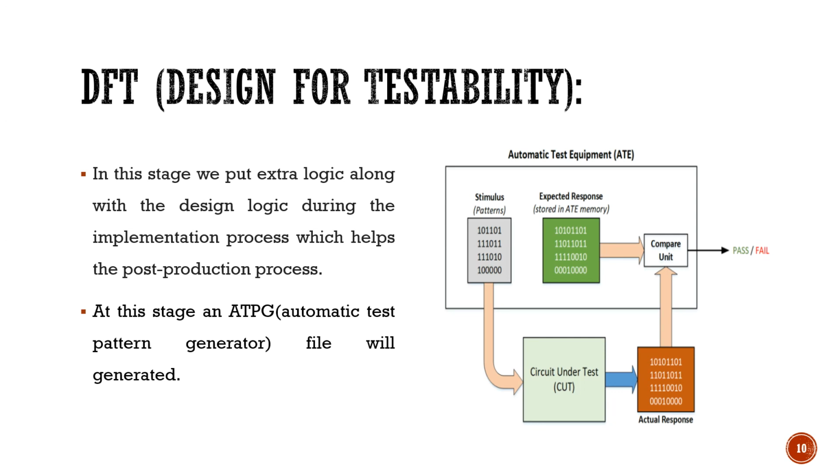And the next step that is involved is design for testability. In this case, after doing the synthesis process, we have a circuit under test, and what we are going to do is add an extra logic into our design. This extra logic is very similar to the DFT concept. That is, we introduce a test logic into our design, and we verify whether the obtained response matches the expected response or not.